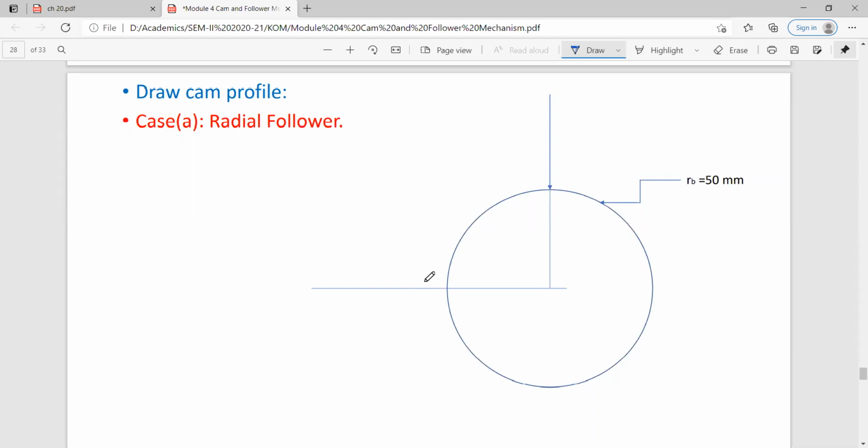On the drawing sheet you can draw it, or if you want to first draw it roughly, then try to mention the proportions. For example, if you draw a circle to show that its radius is 50 mm, and some distance comes which is 40 mm, you should take it proportionately, so that if it is 50 mm, 40 mm should look like this.